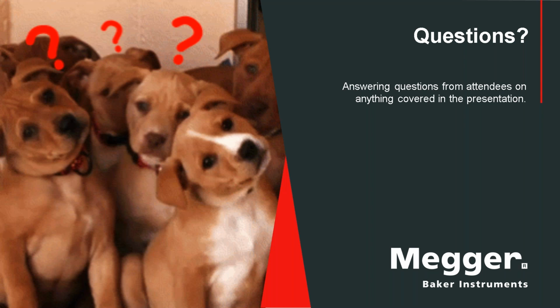If you have a submersible pump motor, you know, 100 foot underground, or a drilling rig, right, a motor well under the earth, you're not gonna be able to get accelerometers on that kind of stuff. I know we had this one case study from NASA where they had these hydrazine pumps that are volatile chemicals, and they don't want their employees around those, so they couldn't go out there and take vibration. And so now we have a scenario where I can't get an accelerometer on, but I can use the motor.